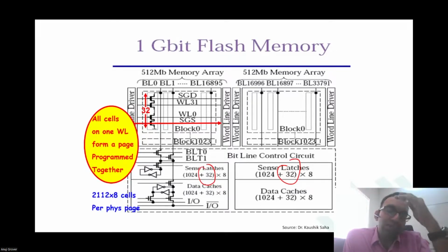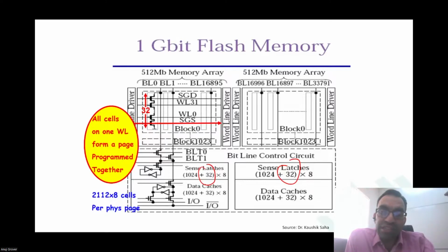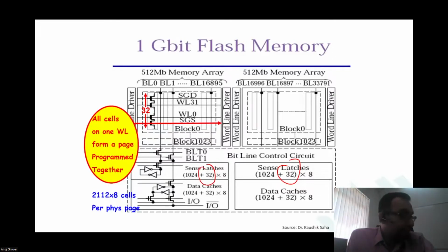Okay. So error correction codes are used so that if there is some error, either at writing or during read from a particular digital circuit, by storing the codes there, I can first detect that there is an error, then decipher what the error was and correct the contents of the memory. This is extremely necessary for Flash. There was a point in time it was also extremely necessary for DRAMs. It adds error resilience in the presence of noise. So you will see that error correction is used widely.